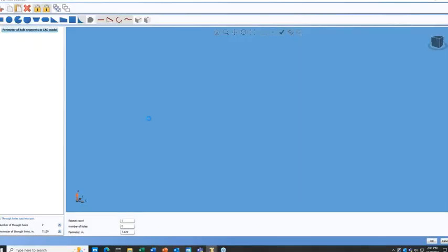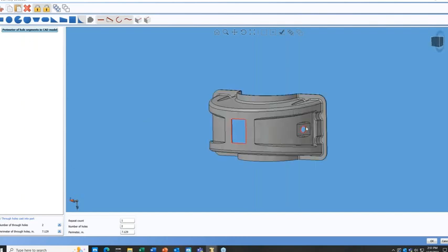And I've specified the through holes using the CAD model, as these two holes shown in red with a perimeter of just over 7 inches. I've counted up surface patches on the part and typed in that 207 value. I've specified a tight tolerance, the highest quality finish, and a more than 4-step parting line. And the side pulls on the left have been brought over from my dynamic costing analysis.